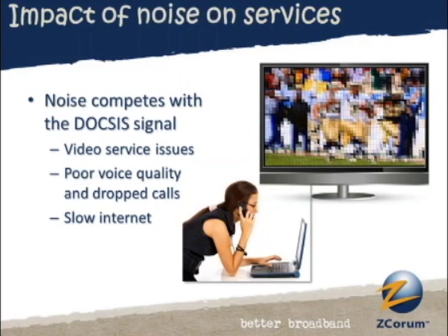I worked with an operator in coastal Georgia, where several years ago they had the G8 summit, and they really didn't see an ingress problem until the G8 summit was getting cranked up, and then suddenly there were a lot more sources of both ground and air-based radar, and this caused them really significant problems for a few weeks, much more than they could actually go fix, because there were suddenly many more powerful sources of RF energy in the area that weren't normally there, and all of the ingress holes that they didn't know about were suddenly being used by this RF energy.